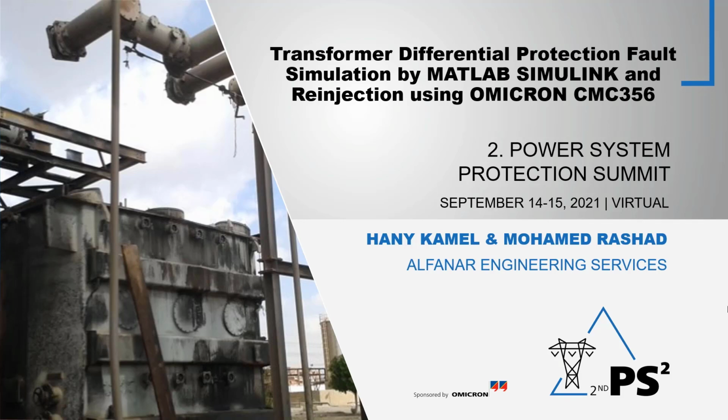We will discuss the Transformer Differential Protection Theory of Operation, and after that we will simulate some faults by using the MATLAB Simulink software and extract the Comtrade file from the MATLAB Simulink to use it again by the software of Test Universe 4.3 to make a re-injection on the protection relay using the OMICRON CMC356 test kit.